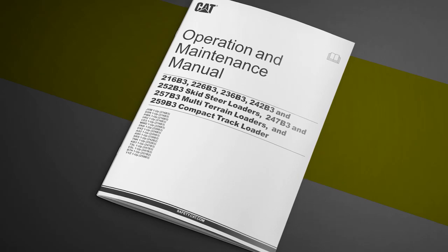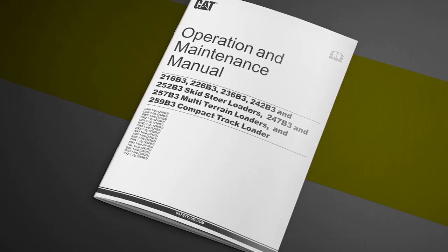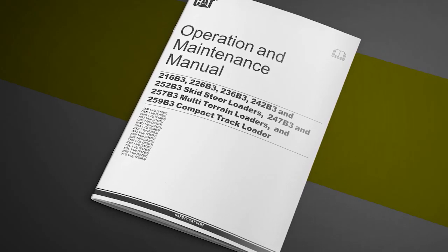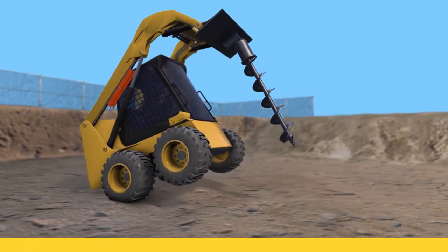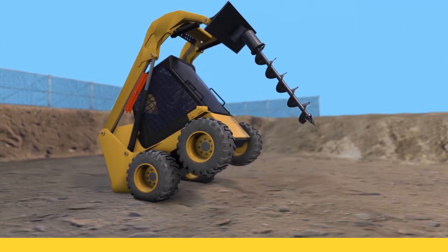Attachments are specific for each model. Never use attachments that are not approved by the manufacturer. Unapproved attachments will put the skid steer loader out of its parameters and cause damage or a tip over.